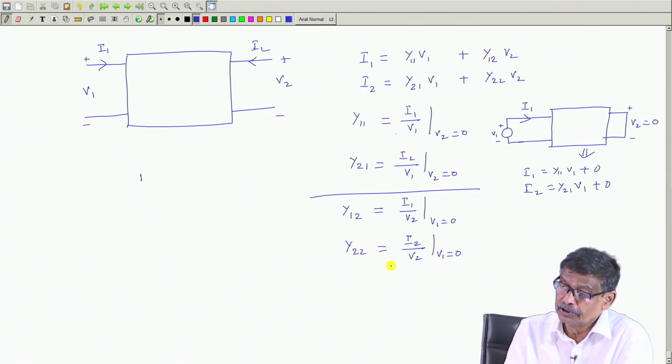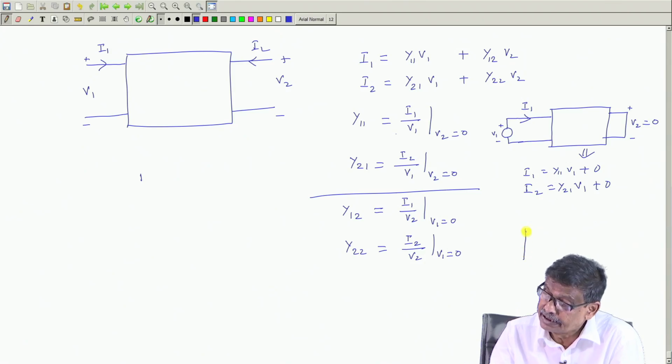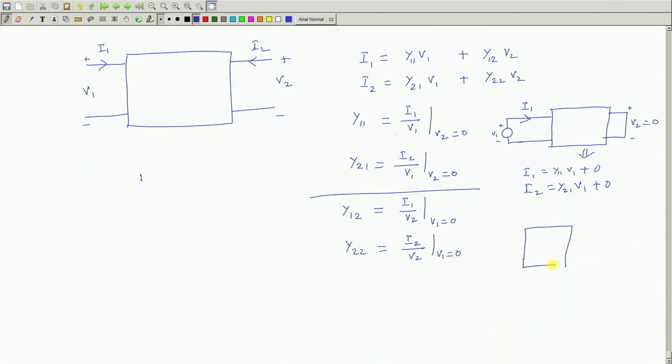So which experiments will give you these parameters? You have to think that okay, this is the two port network, V 2 is below. So I will excite the output port with some known voltage, V 2 I will connect, and V 1 equal to 0, V 1 I will short, and then measure this current. Please forgive me, I forgot to mention this direction of the current, but it remains the same.